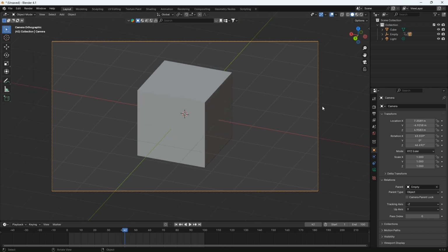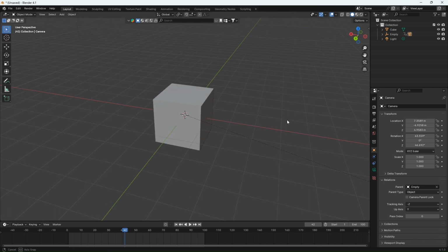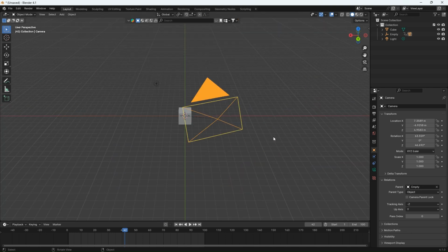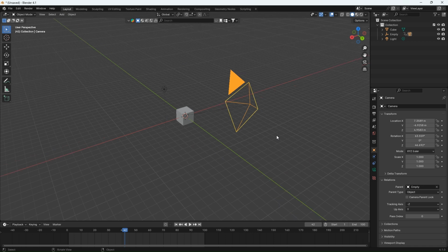So yeah, this is the method of how we connect the axis lines and the camera together, providing keyframes to the axis line. Based on the keyframes, whenever the axis lines rotate, the camera view also rotates around the object. So this is how to connect this. At the end of this video, I will add another video where I did the same operation using a Rubik's cube, and it will show the animation of how the cubes of the Rubik's cube get assembled when the camera is rotating all over the Rubik's cube in 360 degrees.